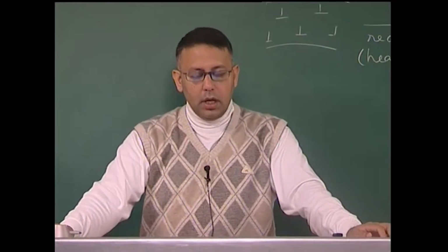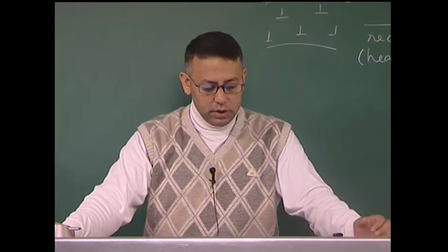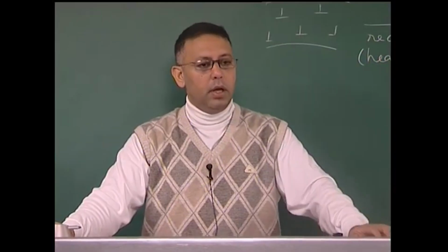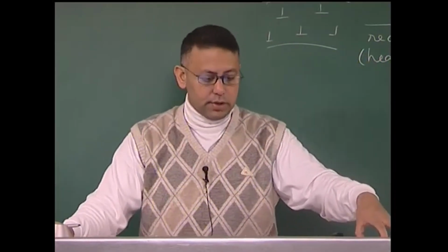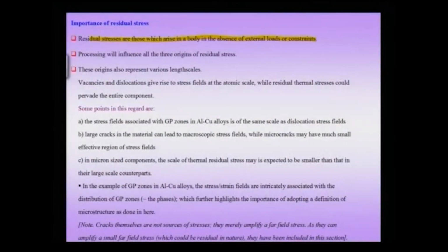Now, we go to certain important points regarding the origin of these residual stresses, and the important question: why am I including residual stresses and their distribution as a part of the definition of a microstructure? We have to note that processing will influence all three origins of residual stresses.